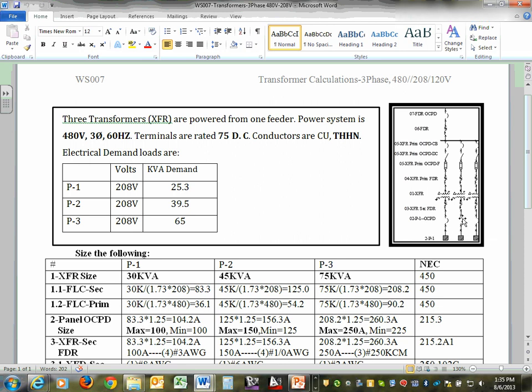Ahead of them is circuit breakers. That circuit breaker can be ahead of them or inside them. When you use SKM PTW, you have to put the circuit breaker out. So these circuit breakers can be inside the panel, it's a main panel circuit breaker. Then I have a feeder coming out of the transformer. It's called O3 transformer secondary feeder. Can you guys see that? Into the transformer 01X is my transformer.